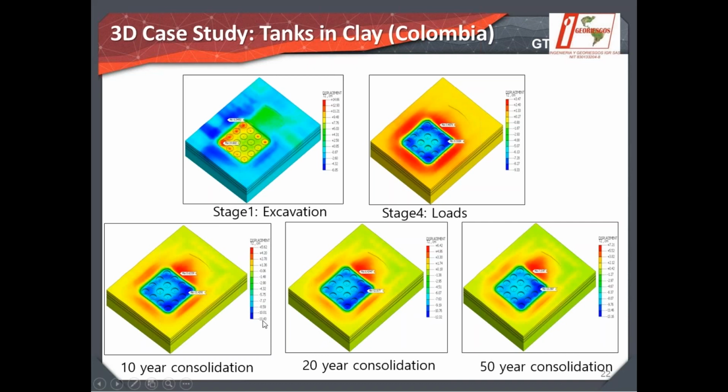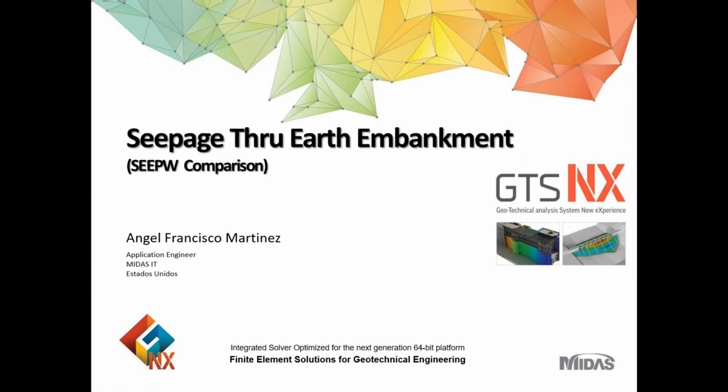10-year, we're looking at it sank around 11.5. 20 years, it sank around 12.3. And then 50 years, maximum sinking is around almost 14 centimeters for this particular distribution. So these are some of the analyses that you might not be able to properly model in a 2D simple case, specifically when you have a higher distribution of all these different geometries to consider. So that's the first case.